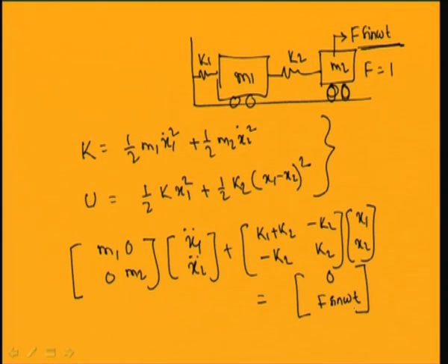So, by writing this equation of motion, you can see that in the previous case the forcing term was 0, now the forcing term becomes 0, F sin omega t. Previously I told you how to determine the response of the system. Now, using this modal matrix method also we can determine that. Already we have found the modal matrix for the system.